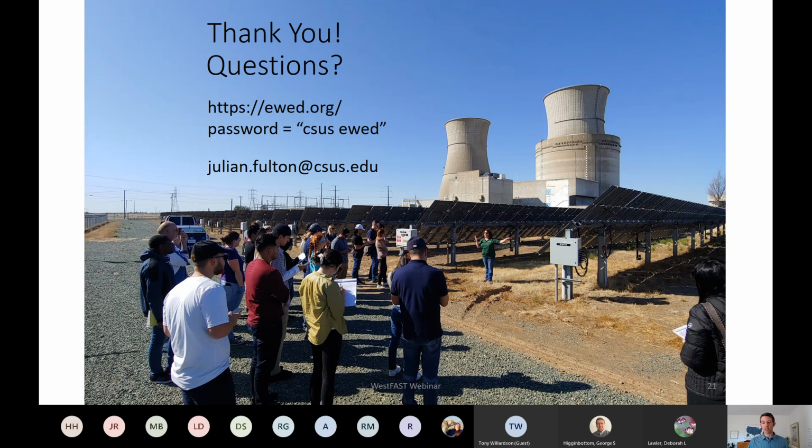I know a bit less about the Salton Sea case, but for most geothermal generation technologies, you still need a cooling system. And you cannot use heavy, very saline water in a recirculating system. You would simply have too much scaling and too many minerals, and it would degrade the system.